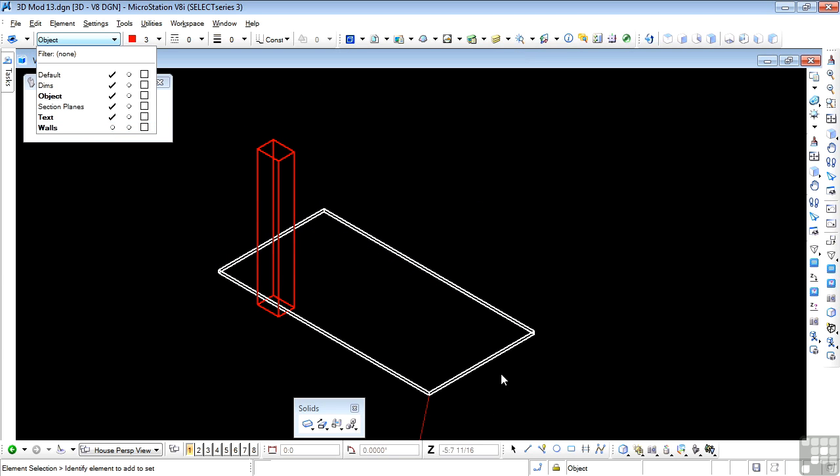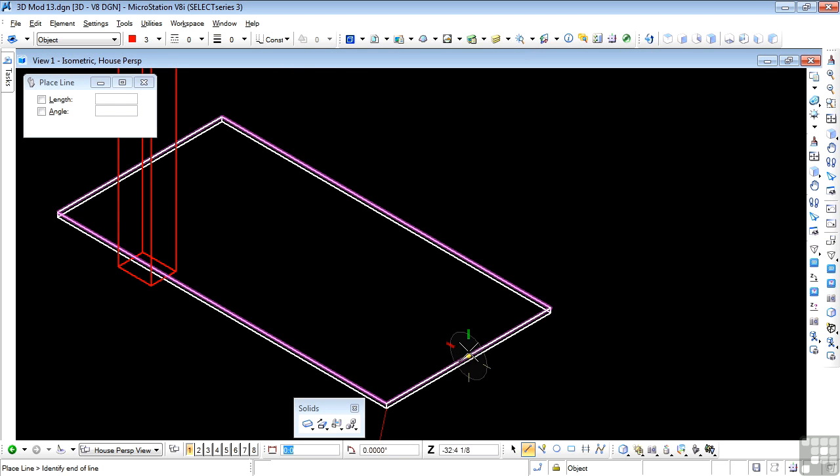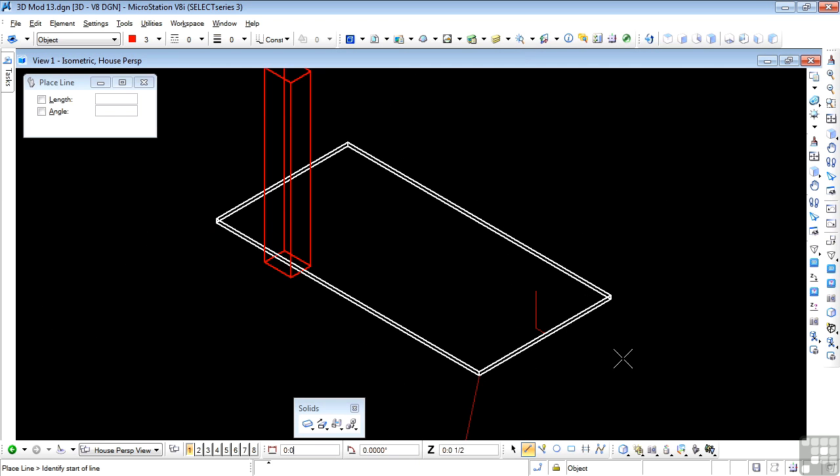Now I can quite easily go in and make my construction lines. So let's do just that. Place line. Construction is still on. My color is still correct. I'm going to snap to, say, the midpoint here. I need the top rotation. I don't want to come too far in, so just a small distance in, doesn't matter how far. Change that to a vertical, and let's go up about eye level for me, round about 5'8" or so. So there's my camera location.